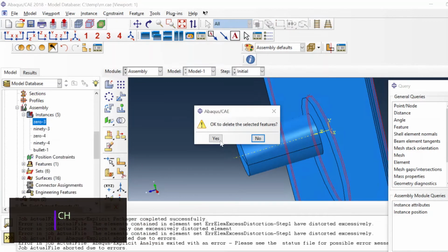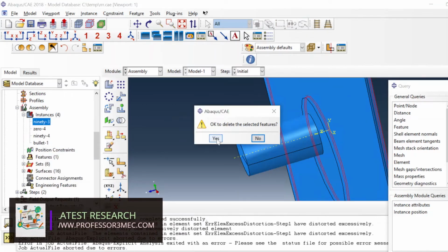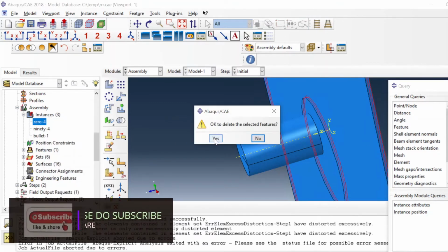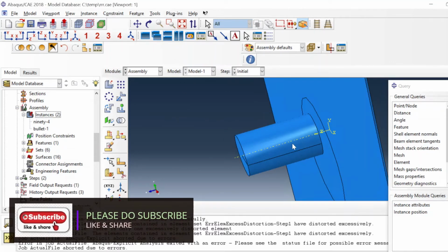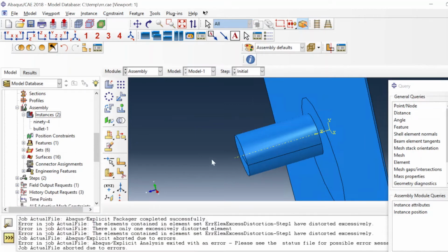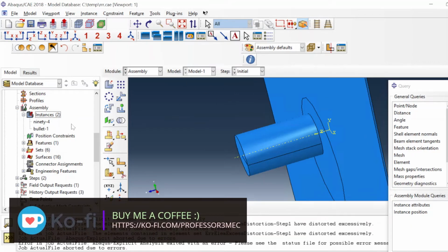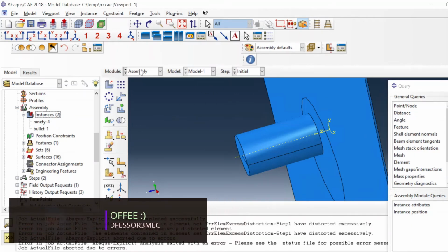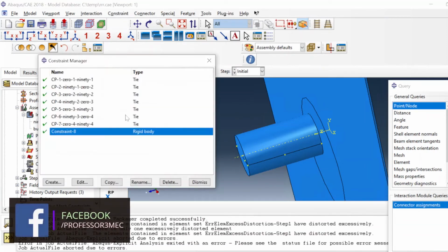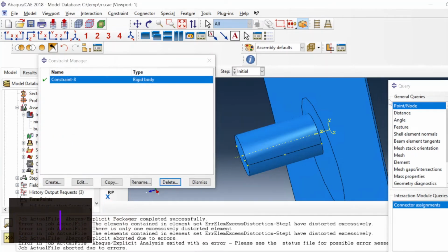So I'm just removing some of these so your computational time is reduced, because I'm not interested in delamination at the moment. Hopefully we can live with this. So now I have only one layer, and it's at a certain distance. Again, I'm keeping the distance the same. You can also reduce the total time from 7.6 to something else, because you don't need that much time now. But let's do this. So now I have only one layer. I need to go and remove the interactions, especially these tie constraints. I'm going to delete all these because there is nothing to tie here now.